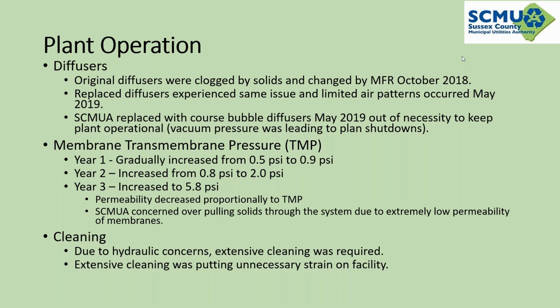They're ultrafine bubble, high efficiency diffusers, but as soon as any sludge gets through any piece of that, they clog extremely quickly. Even when the piece was replaced, we were able to get right back to a transmembrane pressure that we could live with for operation. But as soon as anything got in, the TMP spiked to a point that we really couldn't operate anymore.